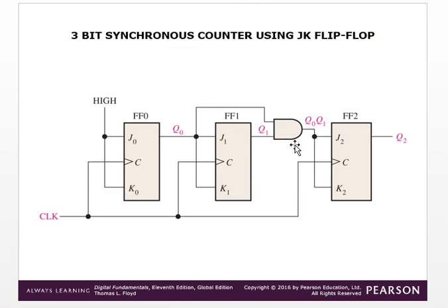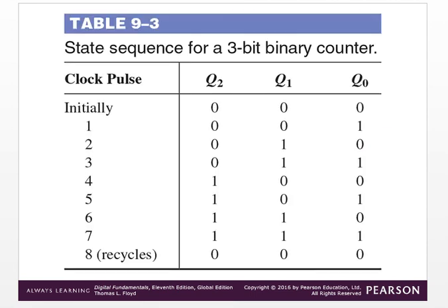Okay, now here another one. See, this is the AND gate. So when you will get 1 1 depends upon Q0 and Q1. How we can explain it? For example, here this is the multiplication of this one. For example, 0 and 0, that means no change. So this is no change. Multiplication of 0 0 is 0, so no change. 0 1 multiplication 0, so no change. 1 0 multiplication 0, no change. 1 1 multiplication, toggle. So here you will get the toggle.